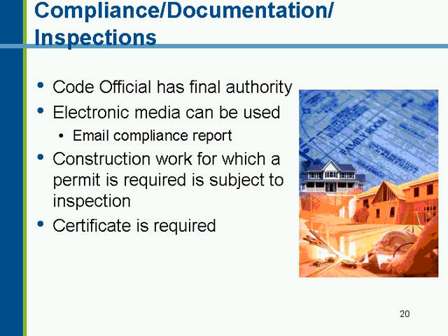Compliance and documentation. Not a lot has changed here. The code official always has the final authority. Electronic media can be used to submit your reports. REScheck has the ability to do that. You can submit your reports electronically right from within the tools, if you would like to, and the building department accepts that method of showing your reports, that they'll allow you to submit a PDF or so forth electronically. And construction work, of course, if it requires a permit, is subject to inspection, and hopefully the buildings out there are being inspected.